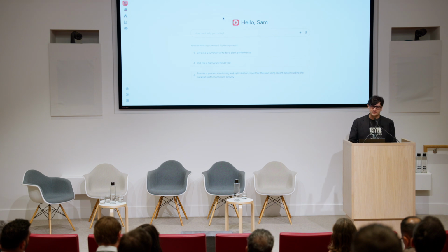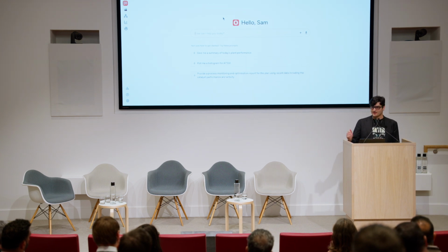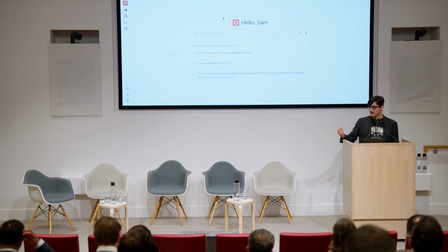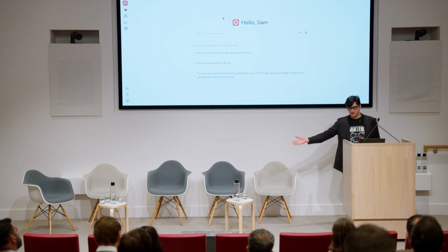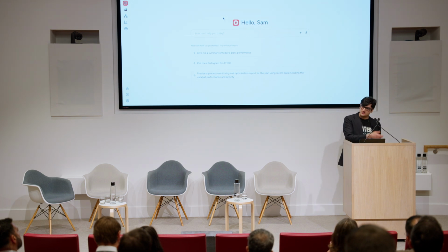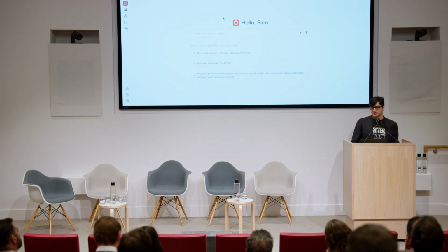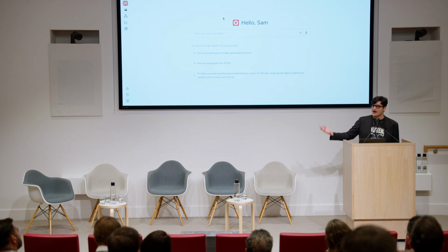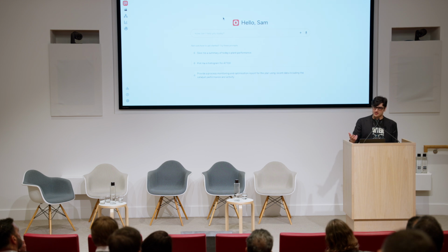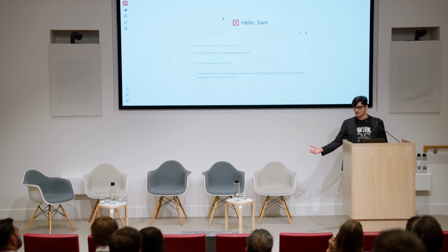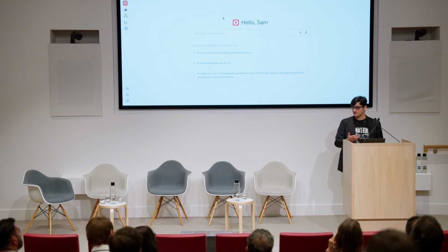But one of the key things they do in the industry, and by they I mean our control engineers in the room, would be to plan what would happen if you were to change something. And this is typically known as what if, or what if scenario planning. As in, what if I change this dial? What would happen to my end product? What if I change the temperature of this particular feed? In which case, what would happen to the actual entire process? This what if is the ability for them to simulate changes without having to directly implement them on site, which isn't possible to do given the expense and the consequences that go with the experimentation.